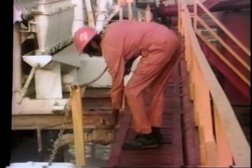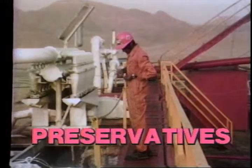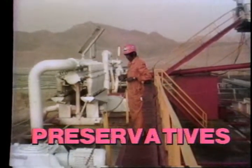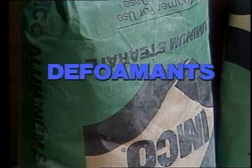Another additive that's needed sometimes to help maintain the saltwater muds is a preservative, because some of the additives, like starch, will ferment without them. And sometimes defoamants, like aluminum stearate or diesel oil, are used because saltwater has a tendency to foam up, like you see on waves in the ocean.